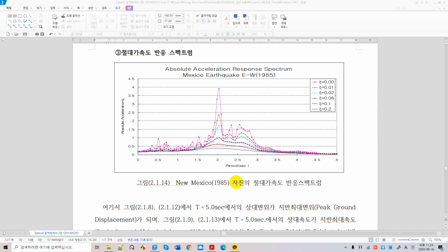So the 0.1 N formula gives you a building period of 2 seconds for a 20-story building. In other words, your 20-story building has exactly a resonance condition here at 2 seconds of the response spectrum, so you get damage. Actually, we had a lot of damage around 20-story buildings in Mexico City in 1985.